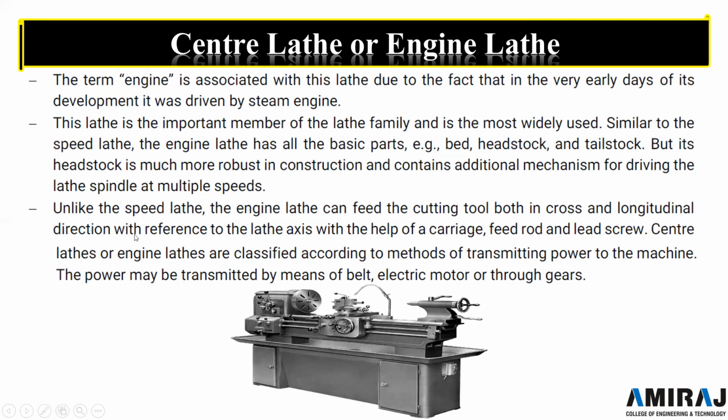Unlike the speed lathe, the engine lathe can feed the cutting tool both in cross and longitudinal direction. In the speed lathe there was a restriction to the cross slide, but here in the center or engine lathe, cross or longitudinal movement is also possible with reference to the lathe axis with the help of the carriage, feed rate and lead screw.